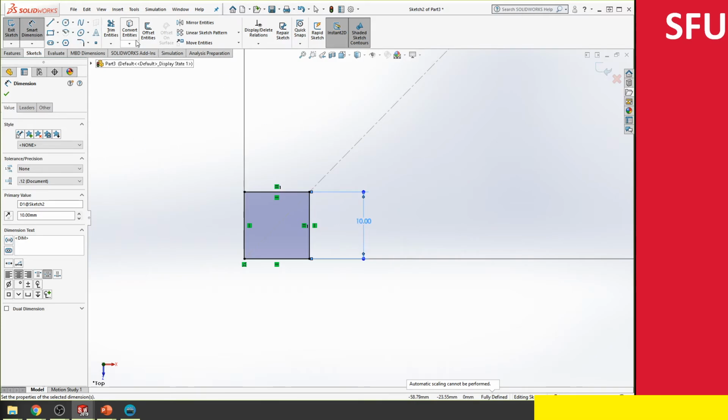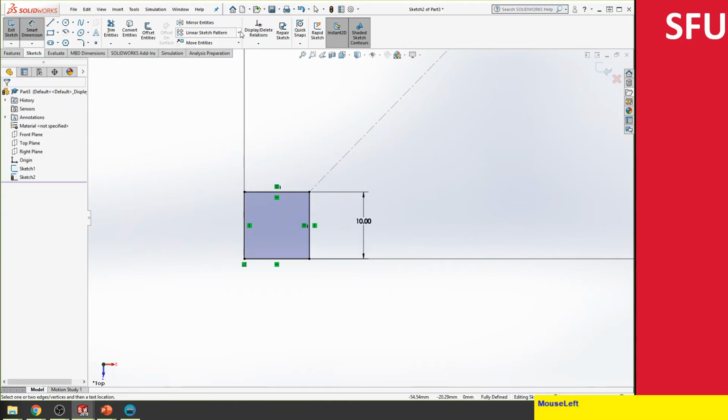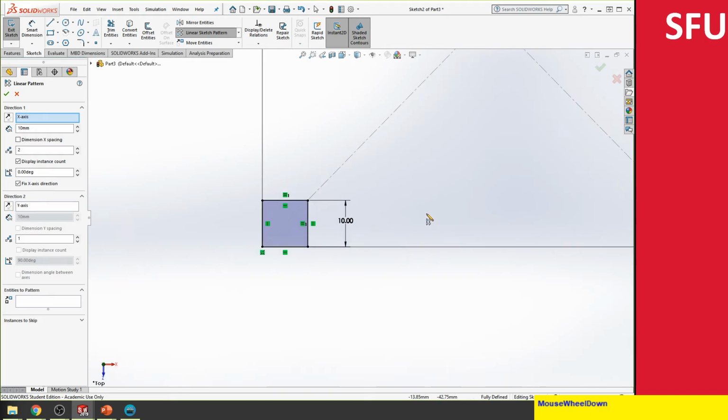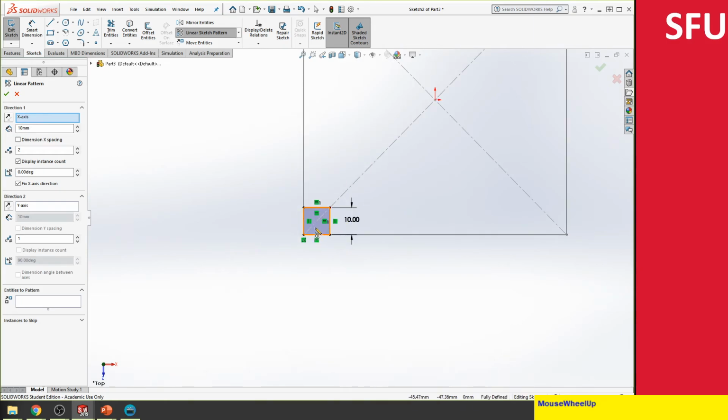So here we will try to do something slightly more interesting. So let's see, this is fairly self-explanatory. So let's see if we can use one of the other ones here. So notice there is something that says it's a linear pattern or a circular pattern. In this case, you could use either one of those, but let's do a linear pattern here. So then it's asking me how many I want in the X and the Y direction. So I'm going to basically want to move this.